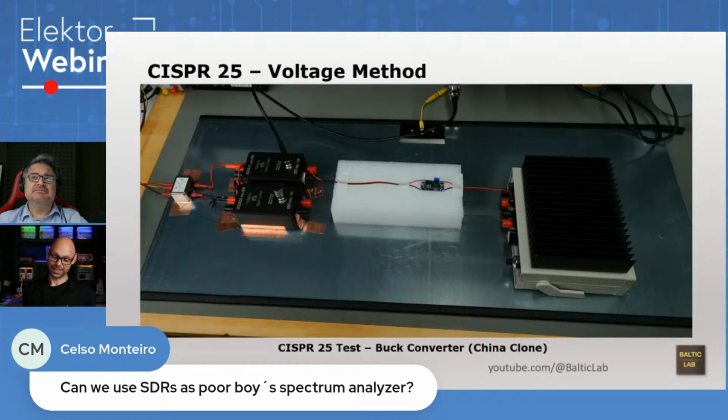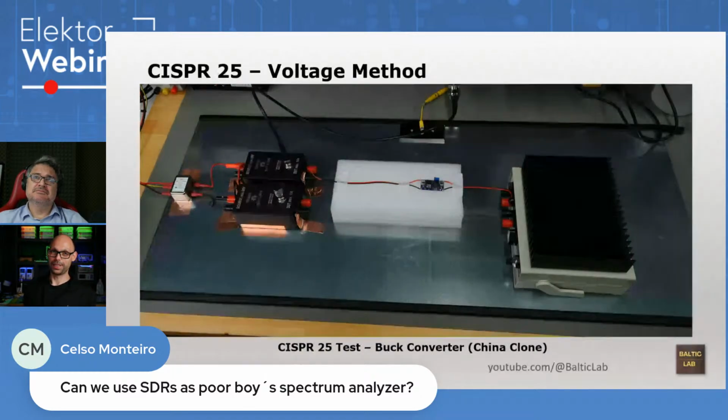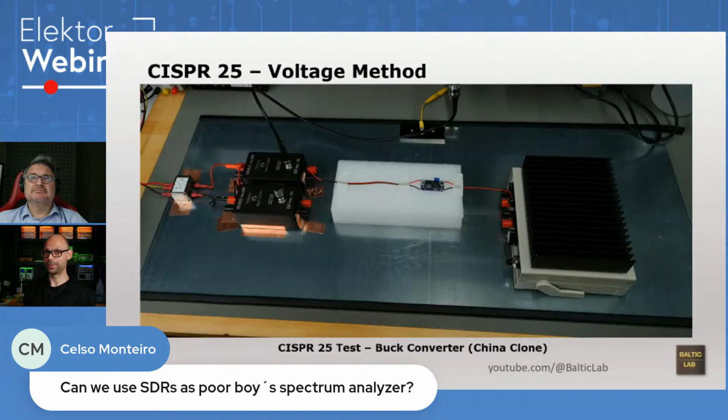Well, that is a very interesting case where everything is compliant, but it still annoys people. That's the funny thing. Just because something is standard compliant doesn't mean it's not going to cause any issues. I doubt that the very old FM radios really meet immunity requirements, but even a modern radio next to a GSM cell phone would give you those sounds. So the cell phone is meeting all its requirements, and the radio is also meeting all immunity requirements, and still you have some sort of interference. This is a really important thing to remember. The standards only dictate certain things in standard conditions, and life happens outside of those boundaries.